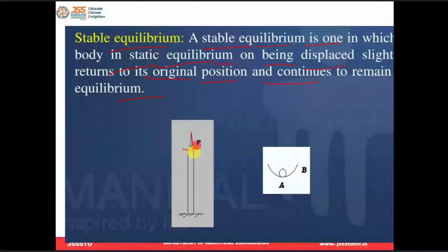The load is applied, so it slightly buckles, it bends. Here we call it buckling, not bending. In beams, when it deforms, that nature is called bending, but here we call it buckling.